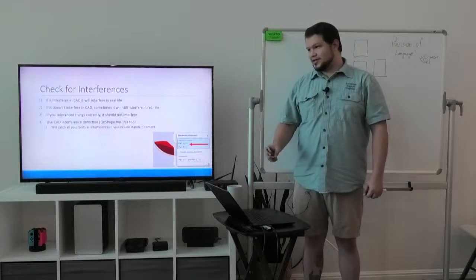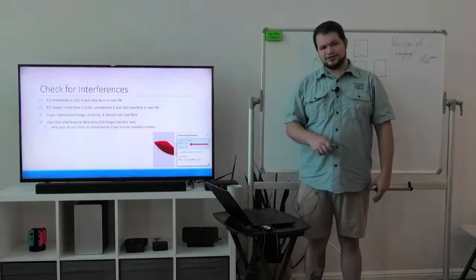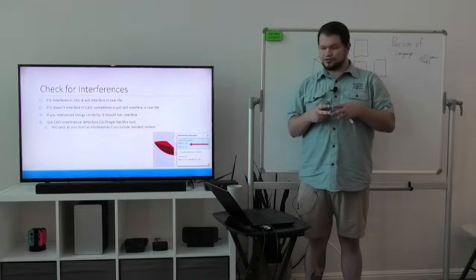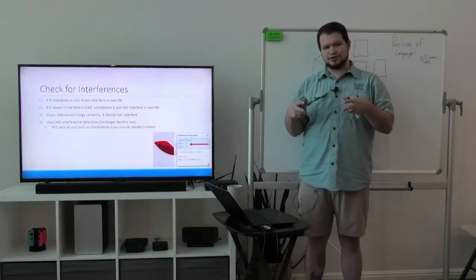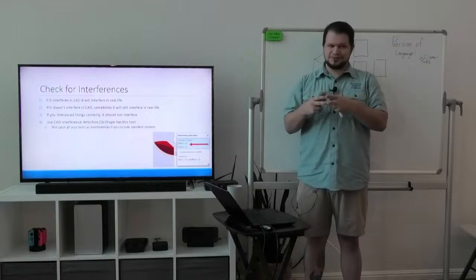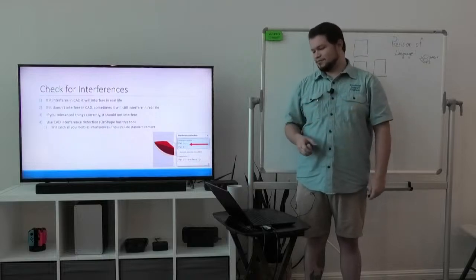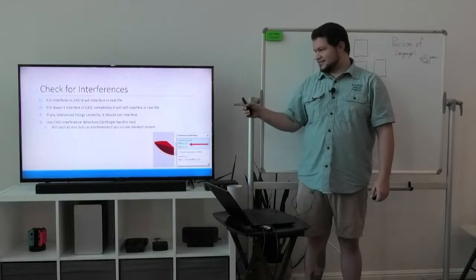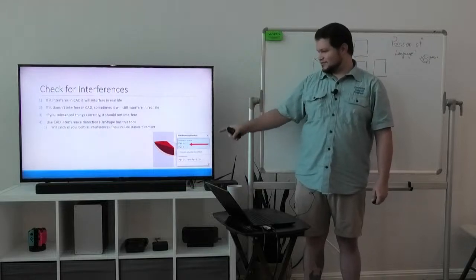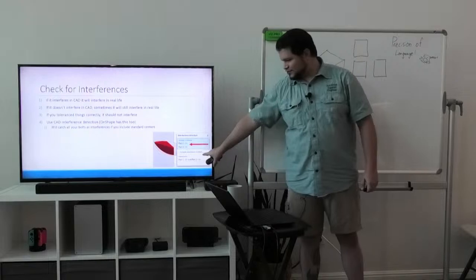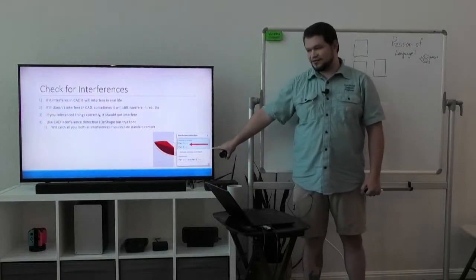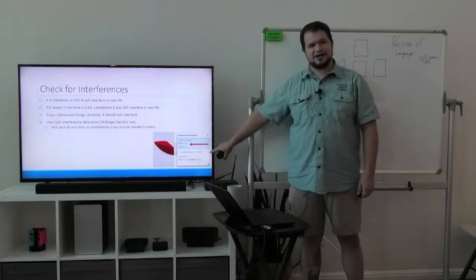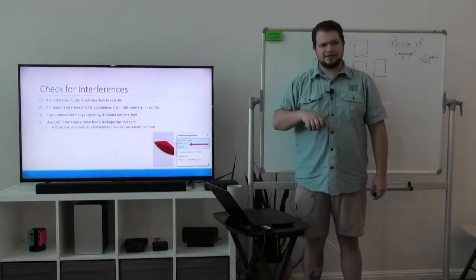It will catch any bolts that you put in there as interferences, because the way we model bolts is without the threads to the biggest diameter, and the way we model a tapped hole is without the threads to the smallest diameter. So there is interference there, but OnShape has a handy-dandy little option, which is right there, include standard content. And if you don't check that, it won't look at your bolts. That's one of the benefits of using the bolts built into the standard content rather than pulling in your own bolt files.